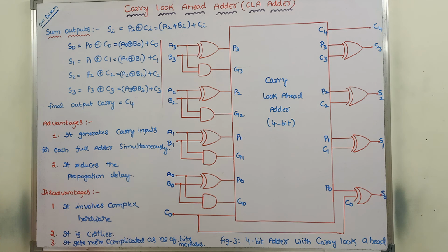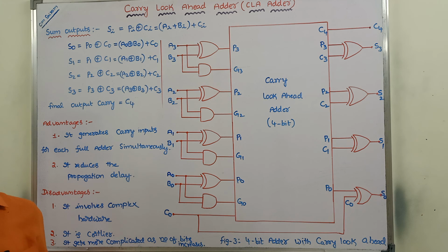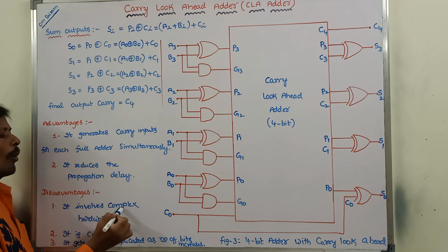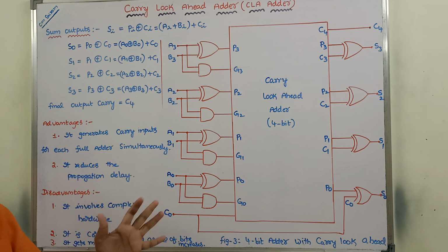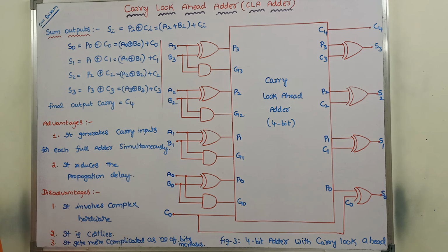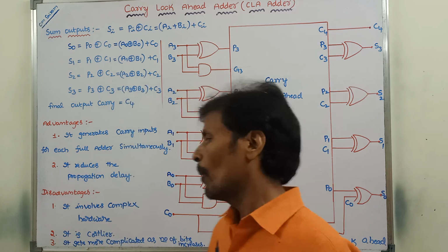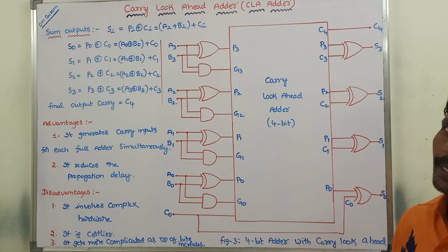Next, disadvantages. To generate all the carry bits simultaneously, it requires complex hardware. Whenever it requires complex hardware, automatically it is costlier. When the number of bits increases, the logic diagram becomes more complicated. So these are the advantages and disadvantages of the carry look ahead adder.